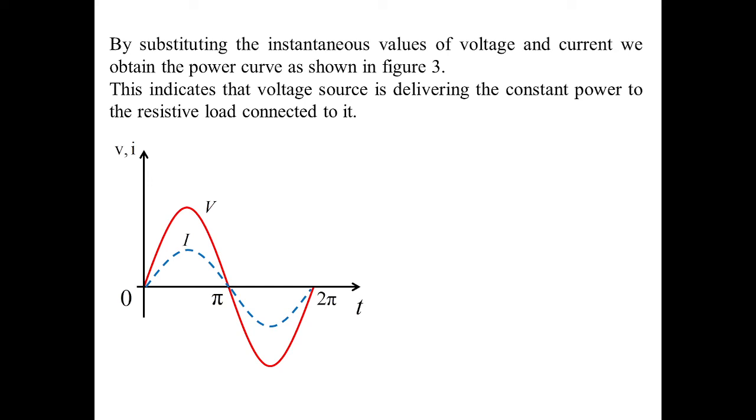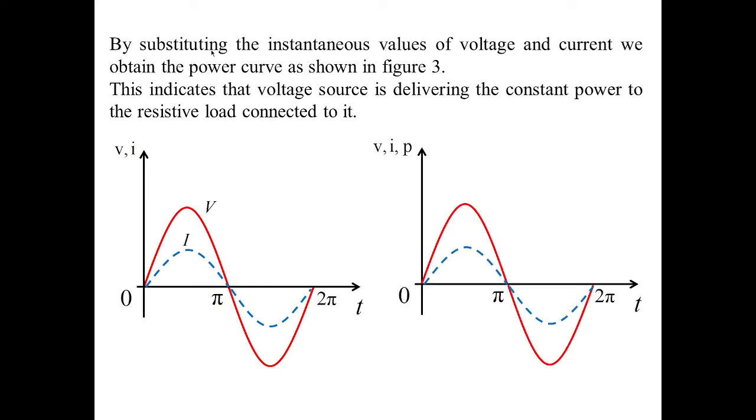So this is the waveform we have, and here we are adding another parameter, that is the instantaneous value of power. Current multiplied with voltage on the positive peak will give you the value of power in this fashion. Now negative voltage with negative current, negative times negative, gives positive power. So I am going to get the power in this fashion.